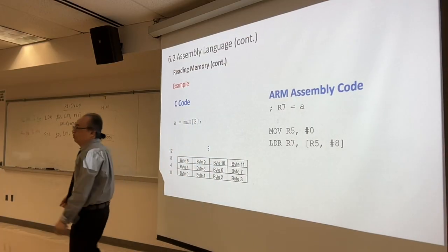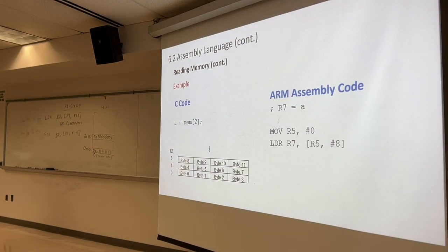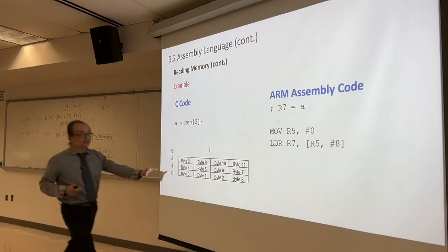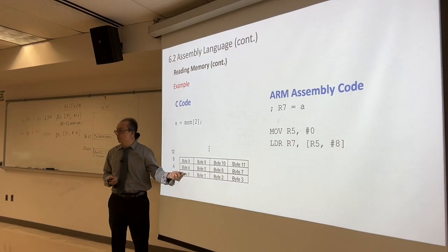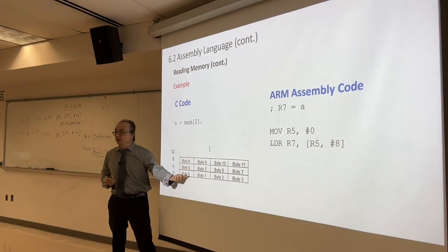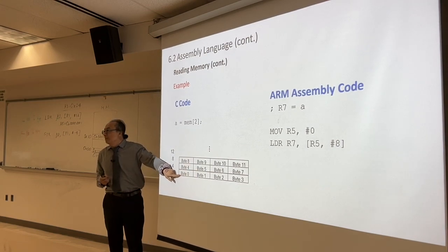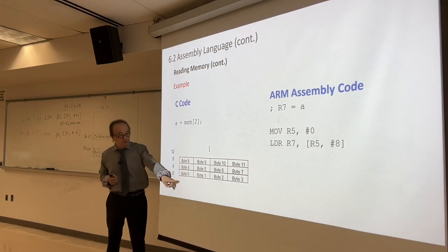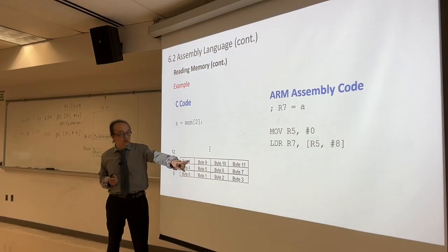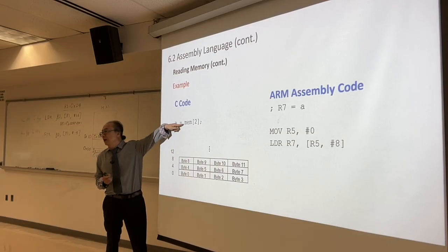Why 4? Why not 2? Anybody? Exactly. One array has 4 bytes, a 32-bit word. This is the big endian, but the memory address is the first byte address. That's the whole memory address. Memory addresses are going to be 0, 4, 8, 12, 16, and so on.